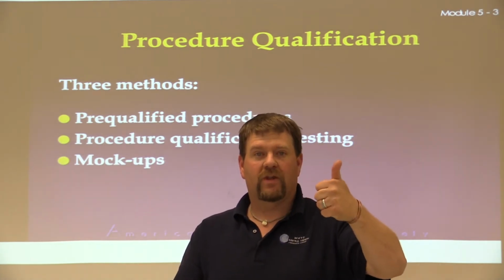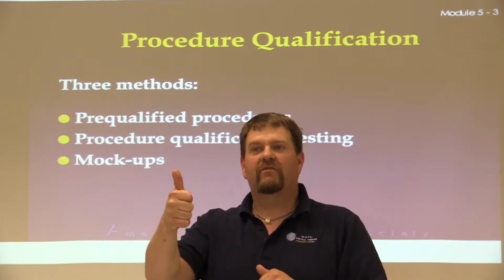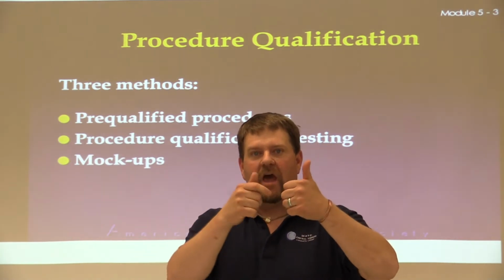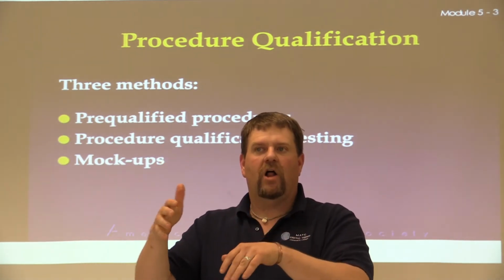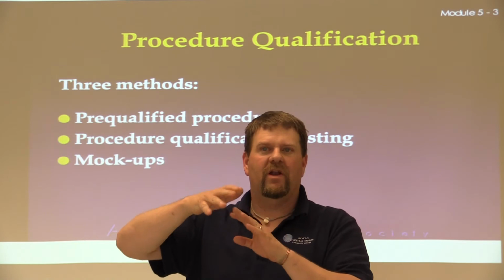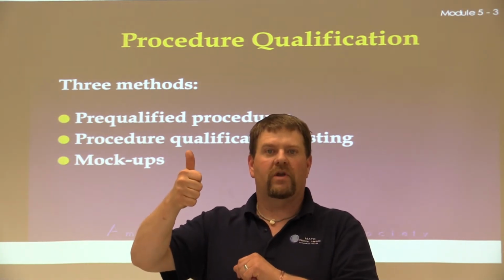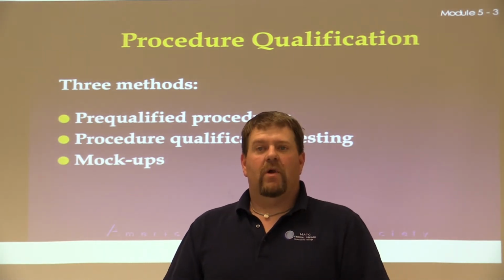And the way we wrote that is, number one, we had to prove that it was mechanically fit. Now we haven't talked about the welder's skill or anything yet. That's the mechanical piece, the PQR, was what told us that it was a good weld, it fell all within code spec. We didn't even talk about slag or anything else. We said the metallurgy alone is fine. Now we go into the next round.